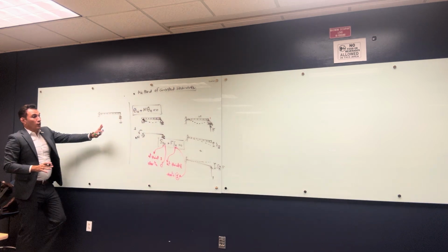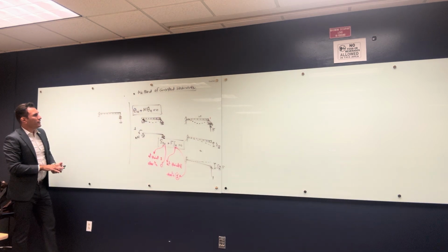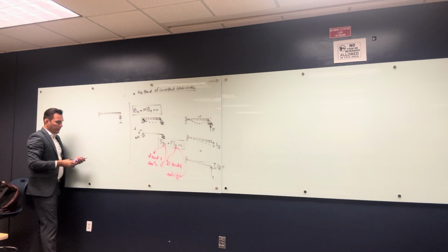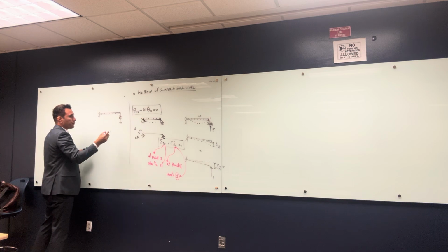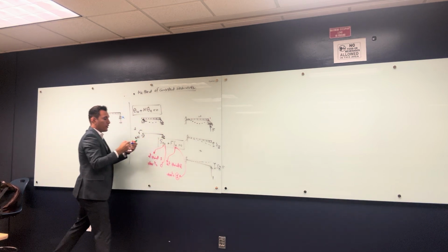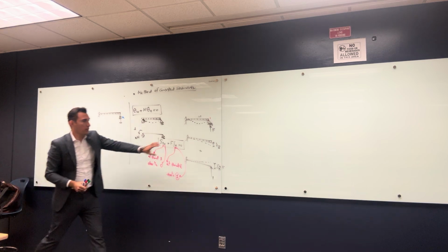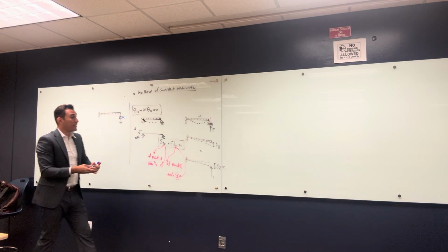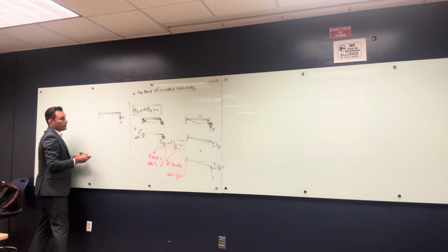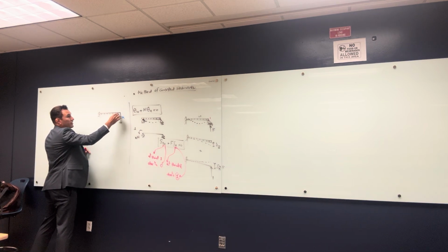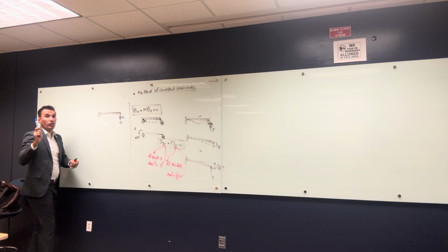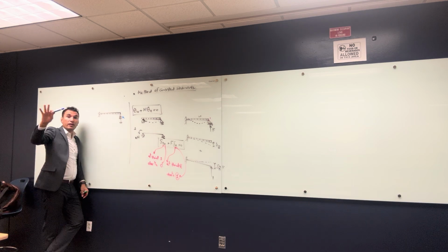All right, so we are done with this part, but what if my beam is something like this? There's no roller, there's a spring, and this spring has a stiffness K. It is the same thing like this one, but like you're gonna have a cantilever, and then you put a unit load, but at the end, the compatibility equation, at this point, this system, when it's gonna deform this point, the displacement is not 0. It's only 0 if this stiffness is equal to infinity.